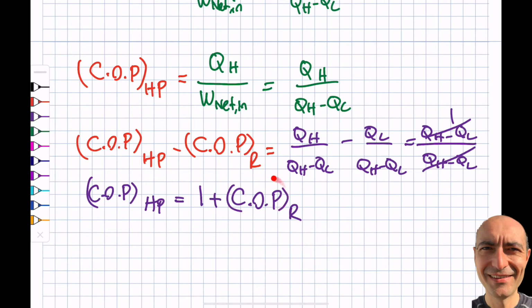And typically the coefficient of performance for a refrigerator is typically 1 as well, or rather more than 1 as well, okay? So you can see I can reach 2. So think about this. It's consuming, for instance, 5,000 watts, my heat pump, okay? But the amount of heat that comes to the inside of the room, if you look here, this is 5,000 watts. But inside of my room, if it's 2, then I'm going to have 10,000 coming in. So it's like magic, per se, from that angle, okay?